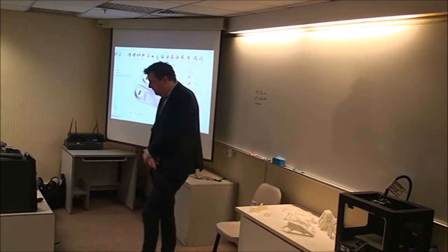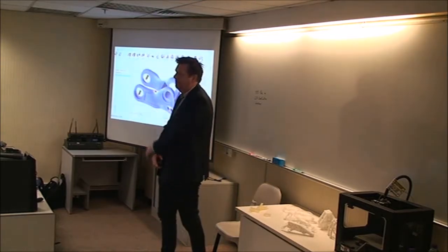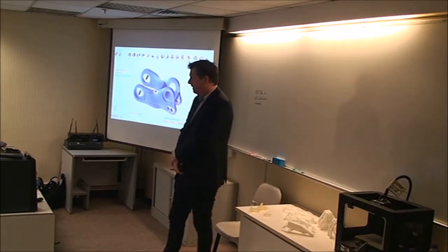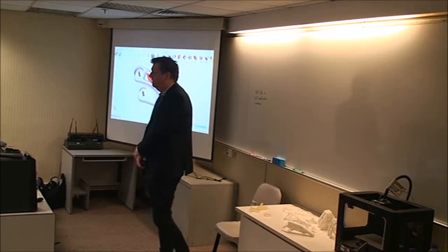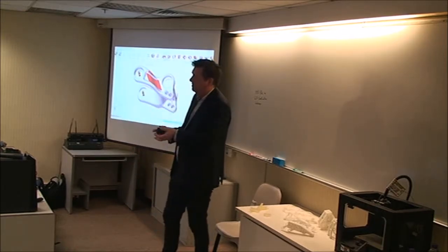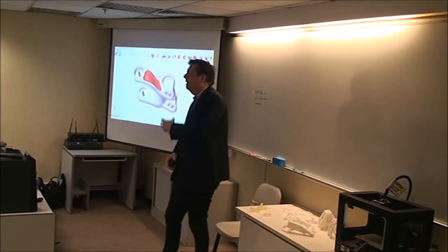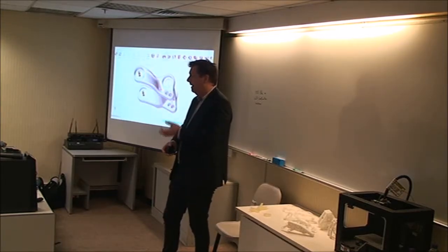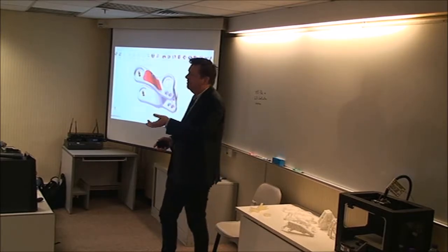And that's just looping around, so that's good. So again, running the model takes a couple of minutes, you get answers. Next stage is developing the design space. So that initial model had the pockets in, might have had the ribs in that lever example I had. So what the next stage could be is to go back and remove all those features that are design assumptions.